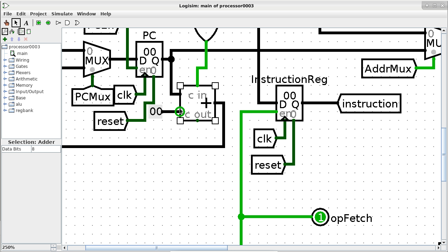So that's why the C out is not connected anywhere? Well, C out is not connected anywhere. That is correct. But the sum is. The sum actually has a path to go back to the program counter, so we can auto increment the program counter. Very good. So anything else that we do not recognize?